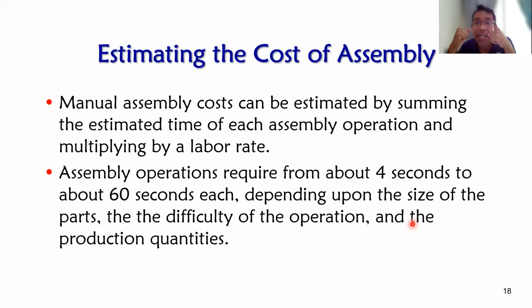For products made in quantities less than several 100,000 units per year, this assembly is almost always performed manually, because they can only be performed by job shop production, for example, by lot production or batch production. You learned that one already. So they cannot invest in automation, because the quantity is not enough to invest in a new machine. So they perform it manually.